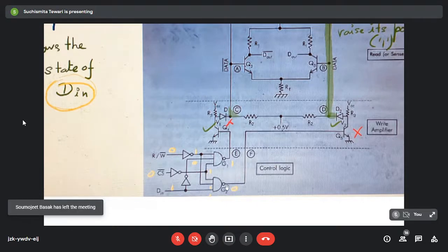Alternatively, if you see the logic over here, here 0 is given. 0 is given to base. So obviously that will send this transistor to cutoff region. It won't conduct, and when this transistor won't conduct, this entire potential is falling here. So actually this D2 will conduct now. Now when this D2 will conduct, what will happen?